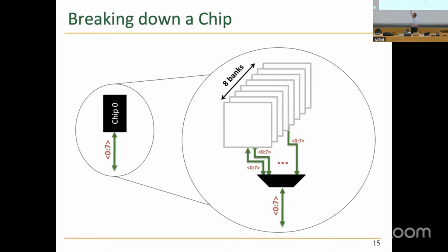In this particular case, we're looking at DRAM. So DRAM is very cost sensitive. So starting accesses concurrently across all banks requires you to send an address to each bank and a command to each bank, which is really expensive. If you want to send an address and a command to each bank, you need to actually have pins to support 8 concurrent addresses and 8 concurrent commands to be sent to each bank.